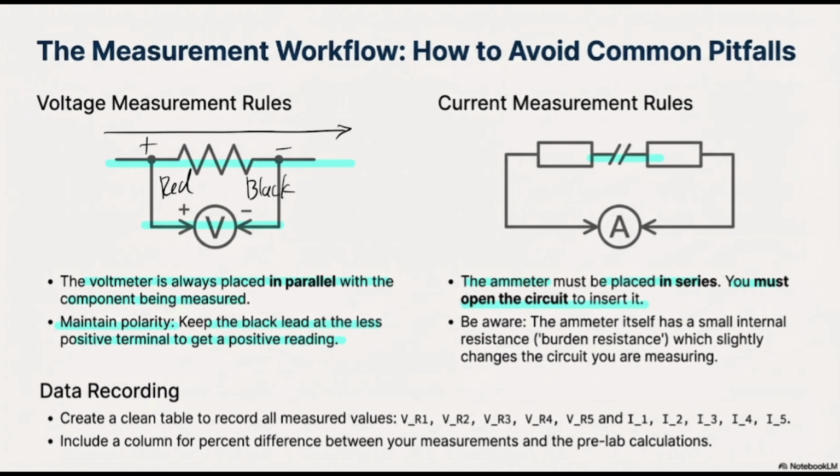Be very careful to not connect the ammeter like the voltmeter, because I've seen tons of times that students do that, but given that the amount of current the ammeter can handle, based on the fuse inside of it, is very little and so fragile, the fuse is going to blow up. So be very careful about that. If you connect your ammeter in parallel like this, your circuit thinks that you have a short circuit. And since we know current is lazy and most of the time it tries to move through the path that has the least amount of resistance, the short circuit is the best option. Since you do have a short circuit, based on Ohm's law, as we all know, I is equal to V divided by R.